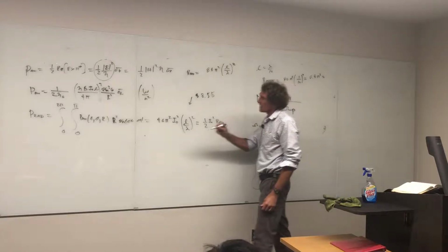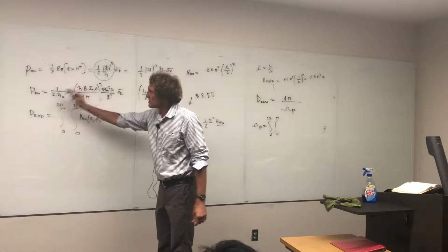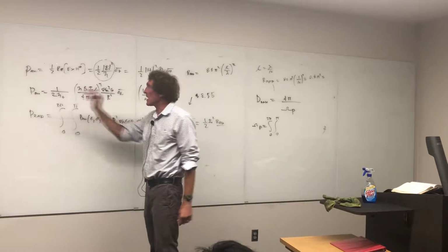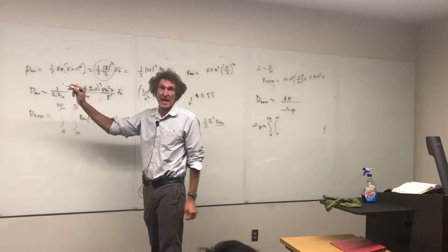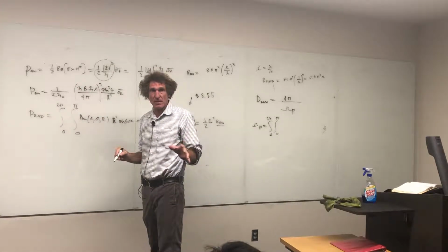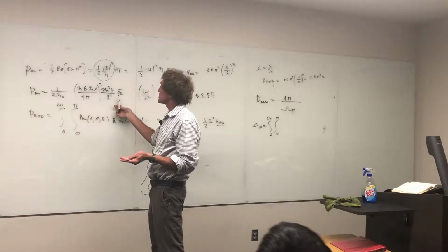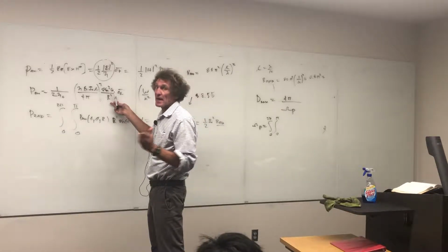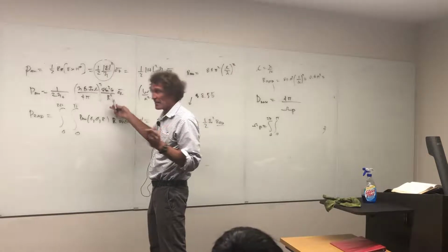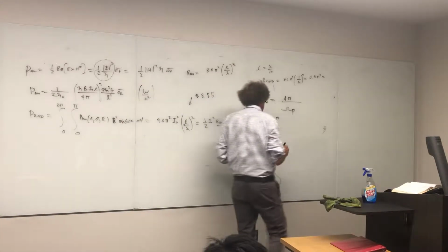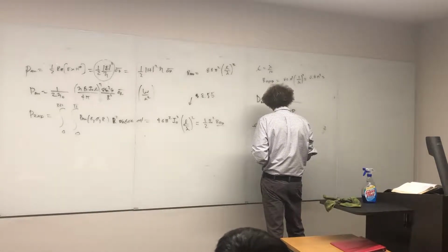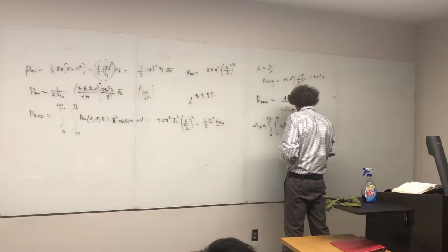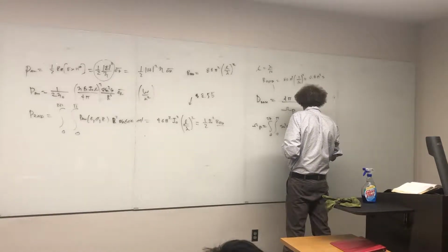Now, this is the thing I was bringing out last time. This equation is the power density, right? Normalized power density means when you divide this thing by the maximum value it can have, you get the normalized power density. Does everybody recall that? Well, the largest value this thing could have is when sine of theta is equal to 1, right? So you would divide this thing by everything but sine of theta, follow me? And you would be left with sine squared. So the normalized power density for that antenna would be sine squared of theta. So you put in sine squared theta, then you put in times the solid angle, which is the sine of theta, d theta, d phi.